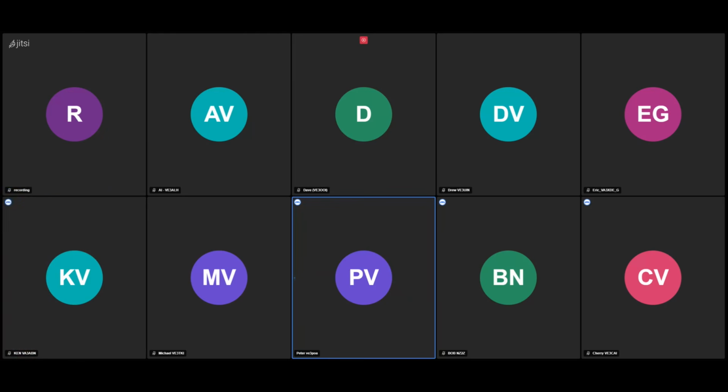And actually, what it turned out to be was the Pico. It has two I2C lines, or ports, I guess I should say. And one port was working fine for the SI5351, but the other port, which was controlling the filter board, was not. So the fix was easy, but it took me a long time to get there.